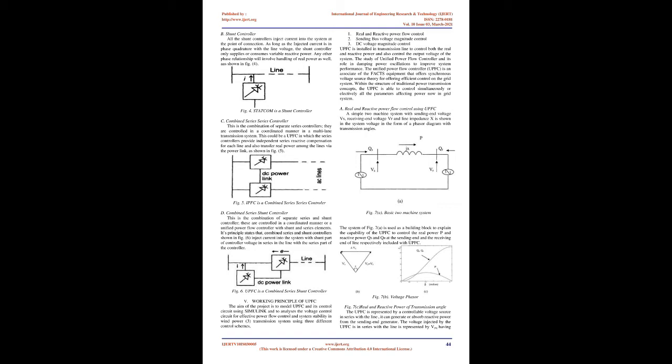The energy storing capacity of this DC capacitor is generally small. Therefore, the active power drawn by the shunt converter should be equal to the active power generated by the series converter. The reactive power in the shunt or series converter can be chosen independently, giving greater flexibility to the power flow control. The coupling transformer is used to connect the device to the system. The figure shows the schematic diagram of the three-phase UPFC connected to the transmission line.